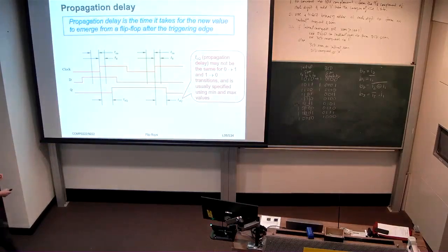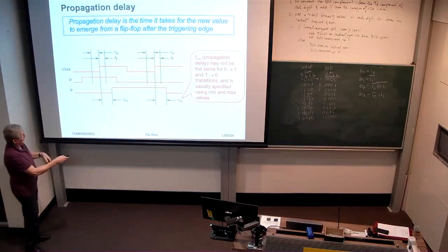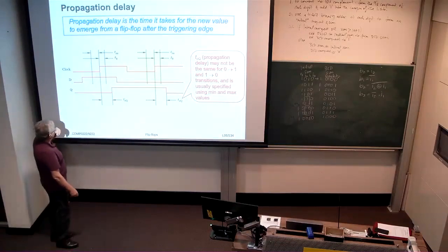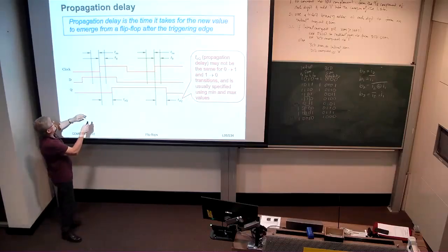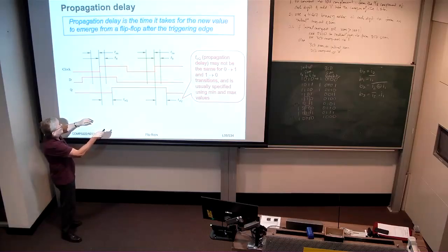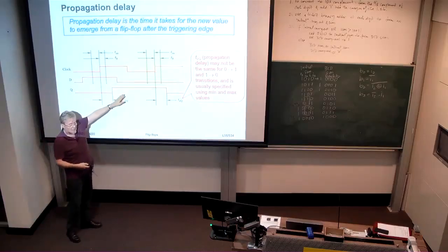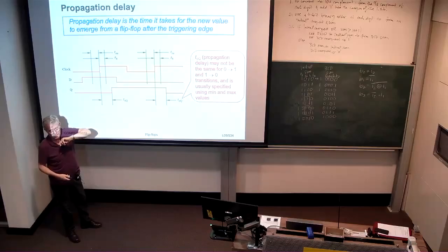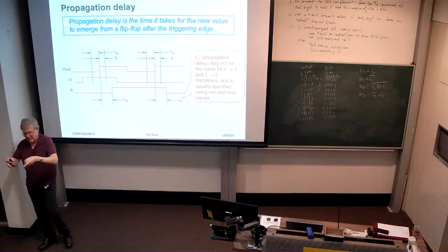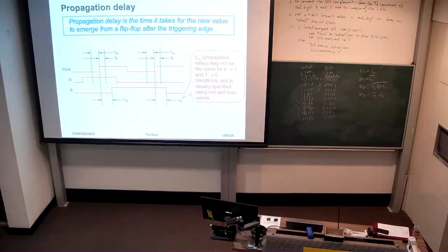So, just looking at a D-type flip-flop, as illustrated here, we have here a positive edge-triggered flip-flop. So we see on the rising edge of the clock, D is high at this point in time, but there is a delay before the output actually goes high. And that's because the gates inside the flip-flop have latency associated with them.